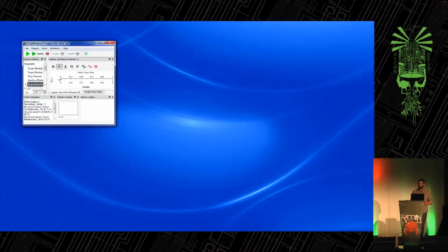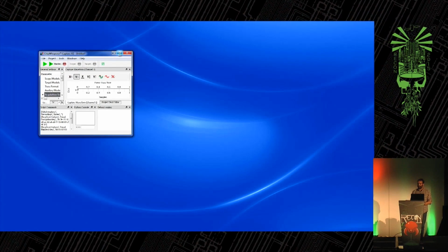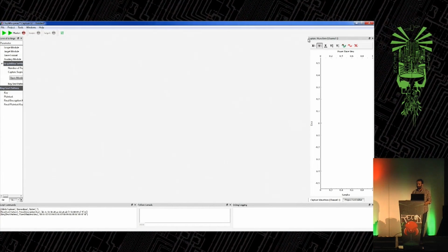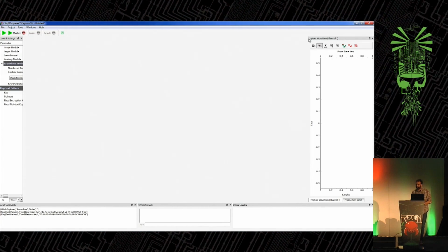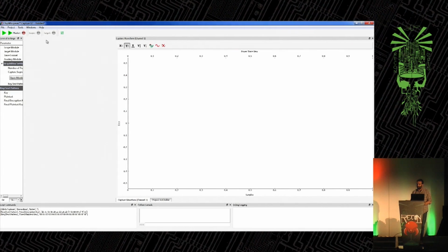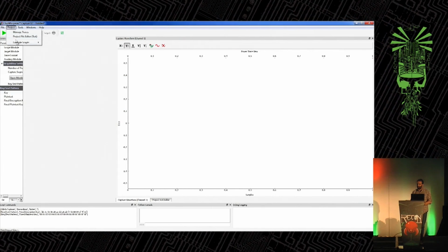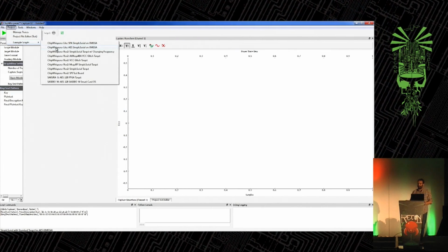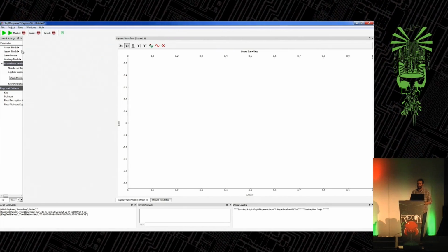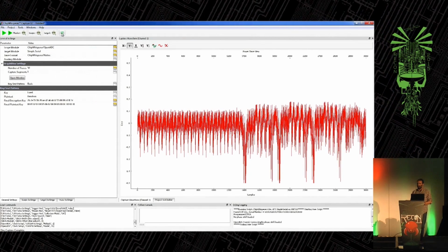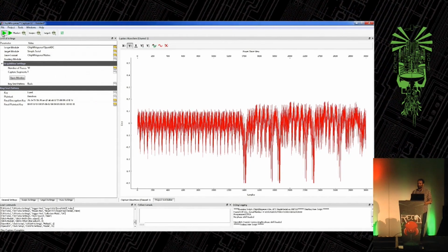Let me pull it over. So this is the tool. It's all written in Python, and it's very fiddly on this monitor here. And it can attach to various targets, so I'm going to be attacking AES on this little XMega board. So what it's doing is it's going to send encryption messages to the device and then record the power.